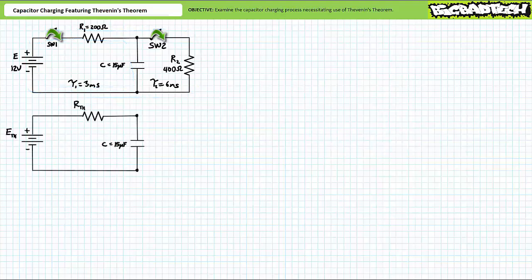Perhaps the easiest and most direct means of analyzing this slightly more sophisticated charge scenario is through the use of Thevenin's theorem, and the capacitor sees the Thevenin equivalent circuit of the more complicated series parallel circuit. Again, the easiest means is through Thevenin's theorem, where the capacitor in question is assumed to be the load of interest. The purely series Thevenin equivalent circuit can then be used to determine the electrical properties of the transient charging process for the original more complicated series parallel circuit.